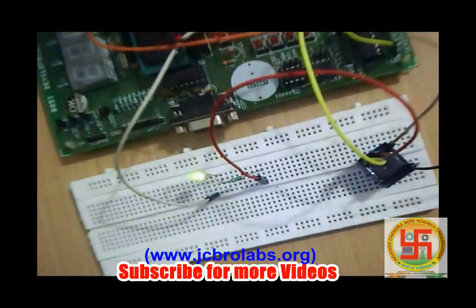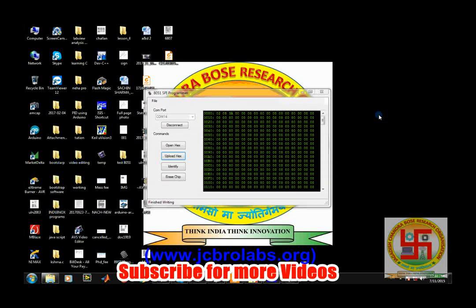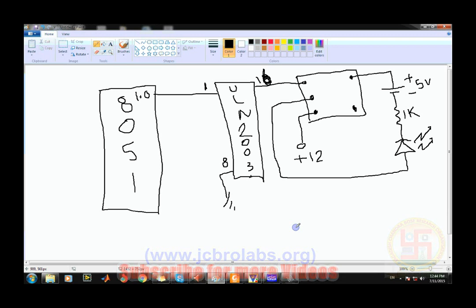So let's move back to the theory lesson. We have seen how the hardware is working, and it's working fine. So this is how we can interface a relay to the 8051 microcontroller. And one more thing, this was not pin number 18, it is pin number 16, because ULN2003 is a 16 pin IC only. So I hope you understand how to interface ULN2003 to the 8051 microcontroller. So that's it for this video. Thank you.